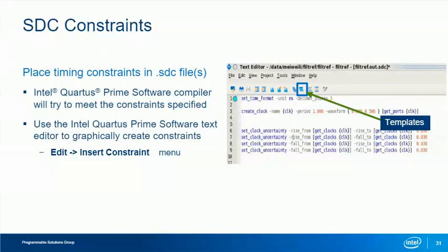It is highly recommended that you properly constrain your designs using SDC design constraints. Constraints consist of commands in the SDC and SDC extension packages that describe the behavior of the circuit. For example, how fast you plan to run the clock, how much external delay there are for each of the data pins, and so forth.